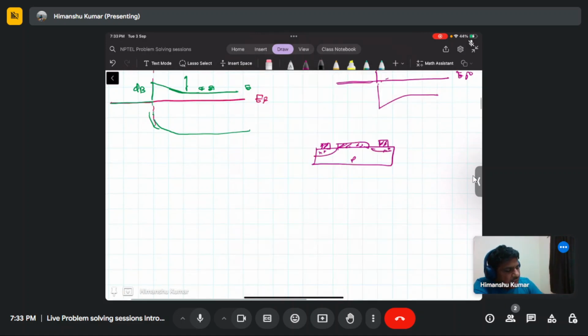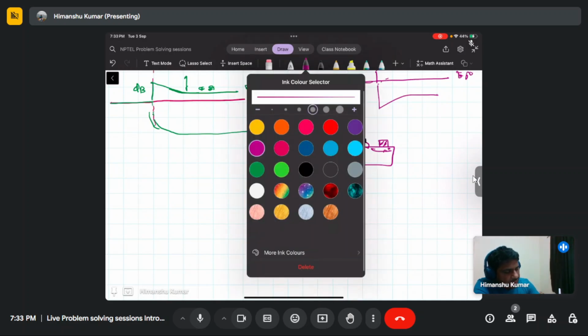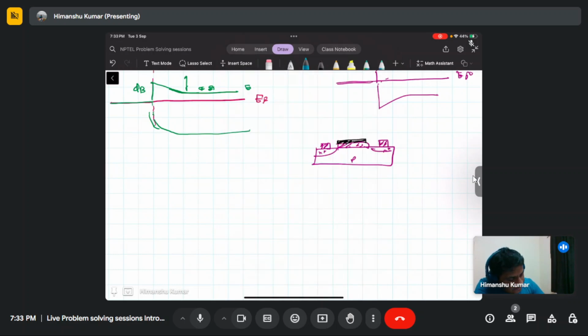If you take the gate region of the dielectric and take a cross section across this device, you will see the metal, plus the oxide and the semiconductor. All the turn-on characteristics and other characteristics of the MOSFET are defined by this MOS capacitor, which forms between the gate, oxide and source substrate region.